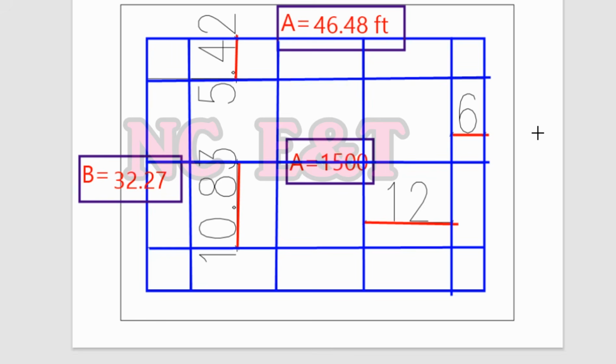So in this way we have made the straight lines, or we have divided this remote area by the lines as per the allowable distance between the sprinkler we have calculated. You can see there are points of intersection between these lines. These points of intersection are the location for the sprinkler which we have to locate. And as we calculated, we need 12 sprinklers for this room.